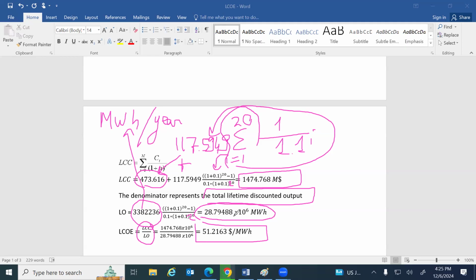And the amount of losses in the conversion? Of course, yes. But mainly, when I give you the power of a plant, it already takes into consideration the losses you are talking about. Whenever I tell you this power plant is giving you this power, I already consider this is the output, the electrical power. I already considered conversion, efficiencies, losses, etc. Because this is related to electricity. But whenever I talk about a capacity factor, this means this power plant can operate the whole time.